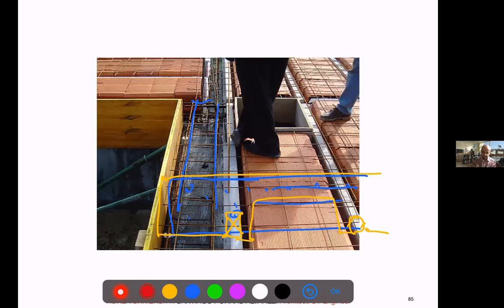Those elements on the border have their own reinforcement, and they will help to have a very well-tied element. Even if we make only masonry walls, it is good to always have one beam tying all the border. And this is what we show here.